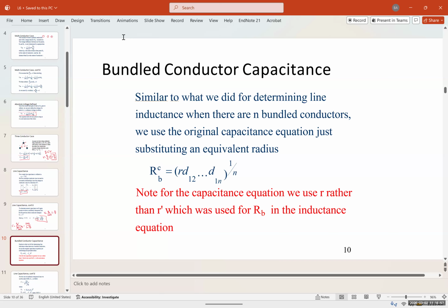But for underground cables, and thank you for bringing that question, sometimes they run for 50, 100, 200 miles, and because the lines are so close, they usually use oil and wraps as insulators. For that, you can't use this equation, okay? That requires a different equation to measure the capacitance.